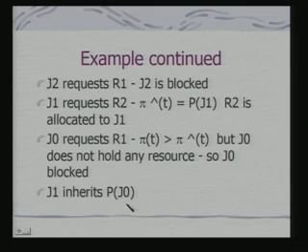So, this is how you manage the resources based on the priority associated with the processes when the processes are competing for the shared resources and resources need to be allocated as an exclusive resource. In fact, this is a very critical problem in a variety of embedded systems, okay? Because if the blocking is larger, then critical deadlines can be missed, and accordingly there could be bugs or faults plaguing the system behavior. It may actually detrimentally affect the system behavior.